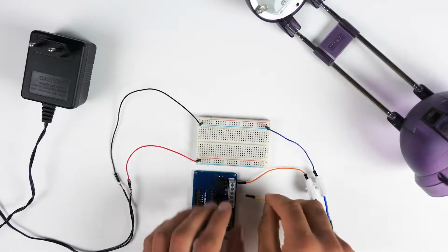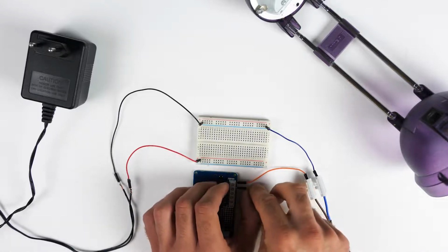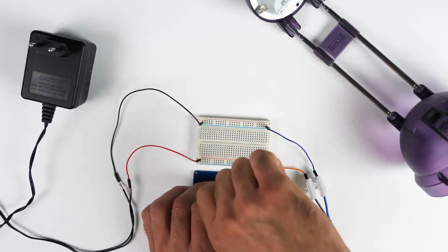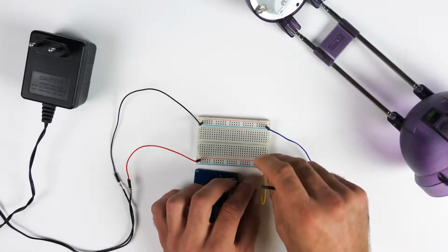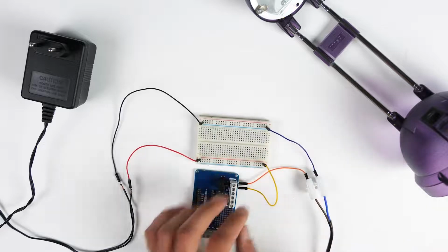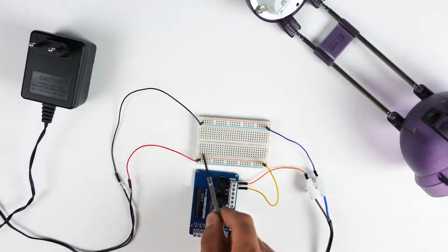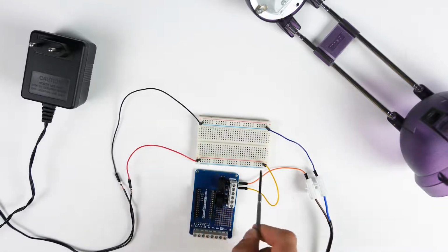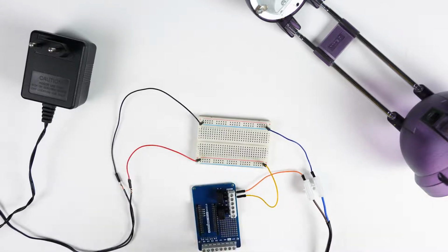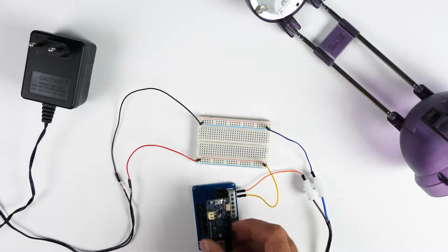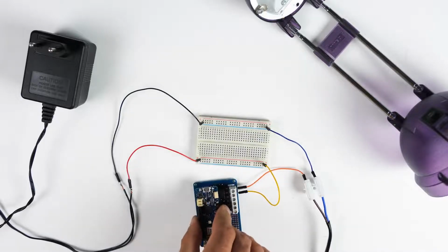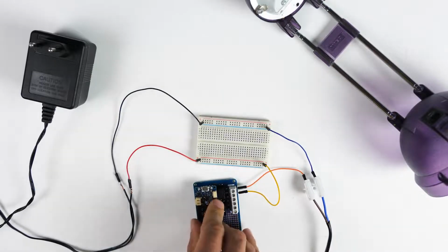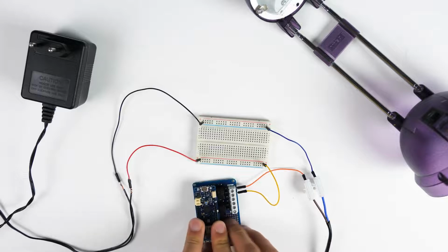And then we're going to connect from the common pin here to the power line on the breadboard. This could go straight there, but we thought this is a slightly nicer setup. And then we're just going to use this Maker Wi-Fi 1010. We're going to align the pins like this, and then push it in. And there you go, there we have the whole setup.